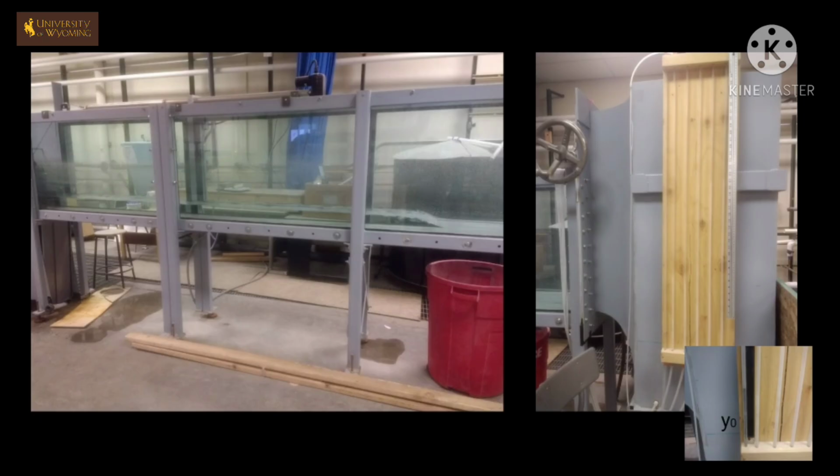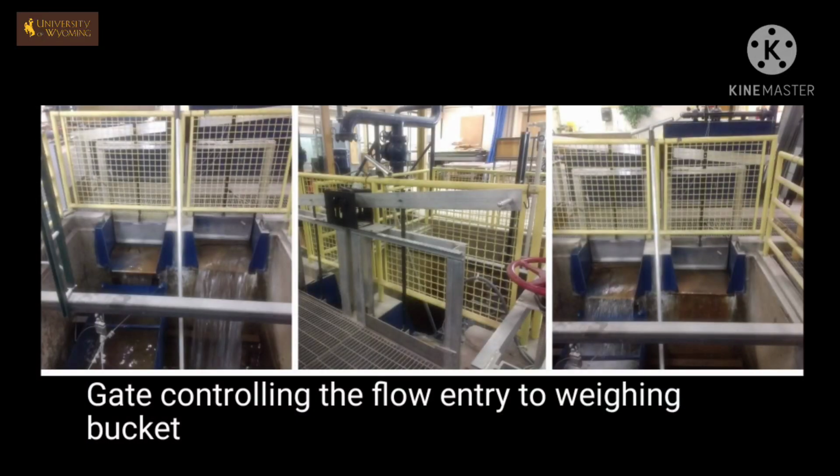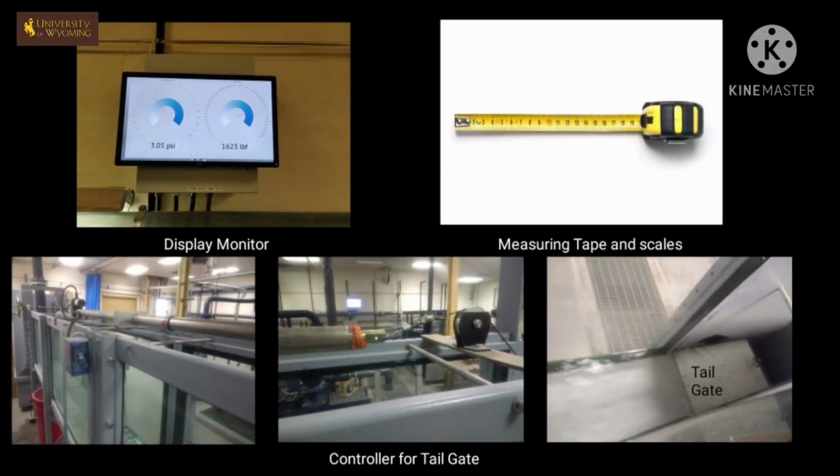The equipment needed to conduct this experiment consists of the flume with the head tank and the tail tank, the weighing bucket, and the gate controlling the entry of flow to the weighing bucket, the display monitor which shows the weight of the weighing bucket, a measuring tape to measure the length and depth of the flow, and a controller for the tailgate to create the hydraulic jump.